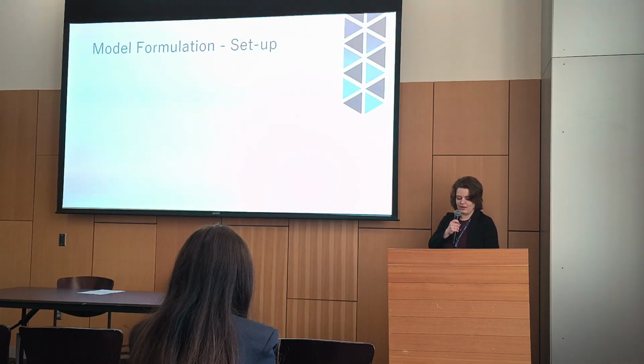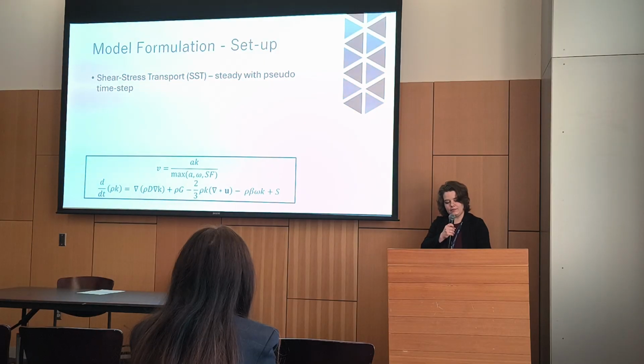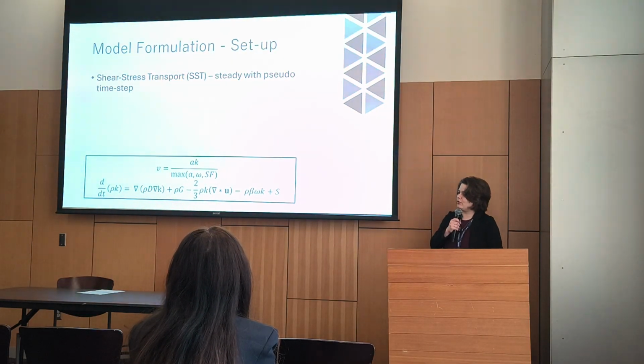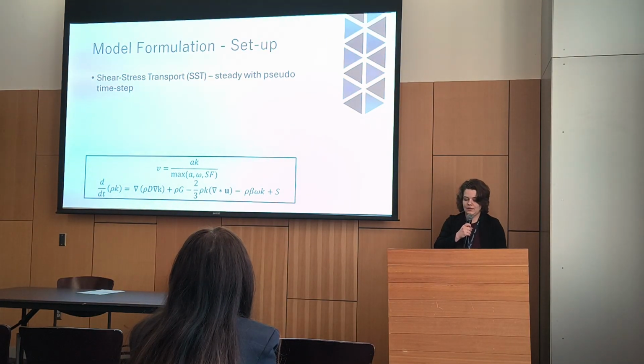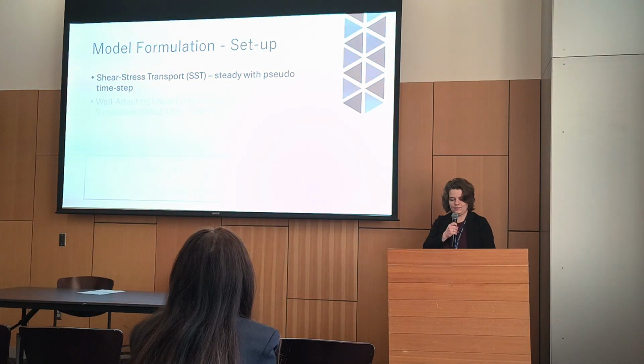But going into the actual setup, a little bit about the actual models I'll be using. The shear stress transport, this one averages things out, and we have the kinematic eddy viscosity as our first governing equation, with the second one being about the turbulent energy. This will be a steady study with the pseudo time set since it averages things.